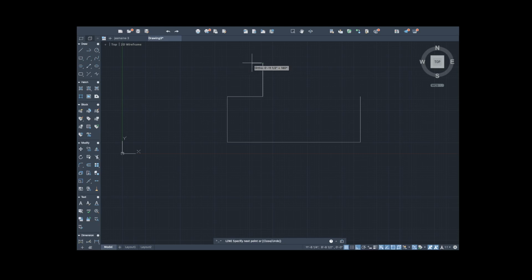I'm going to draw a line this way now. 4 feet, 4 3/4 of an inch. So 4 feet dash 4.75 inches. Remember, 0.75 is still 3/4 as a fraction. I'm going to connect a line right here. And then I'm going to connect a line from this point to this point. And I can delete these 2 lines right now.